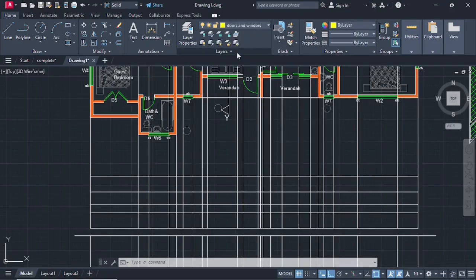I'll select the yellow, then I'll go here where it says rectangle, select that, then we're going to make a window here. There will be an opening, then following this line, press on enter for the previous command here, enter.